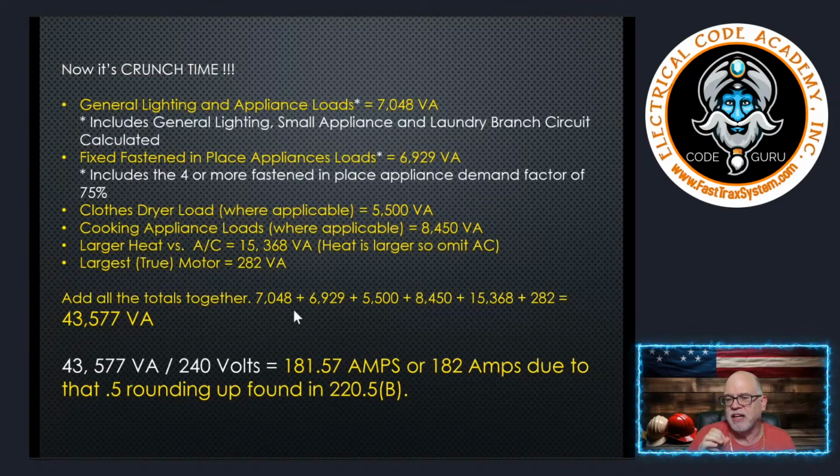And it's 83% of what's marked on the actual breaker. I'll use a breaker, keep it simple, on the breaker or fuse rating. So you'll be 83% of that. And the conductor cannot be smaller than the 83% of the rating. Now, if you have adjustments or corrections, you've got to account for that. It might cause you to go to a bigger size conductor because after those adjustments and corrections, you still can't have a conductor that's less than 83% of the rating of the service or feeder. Makes sense? Okay.